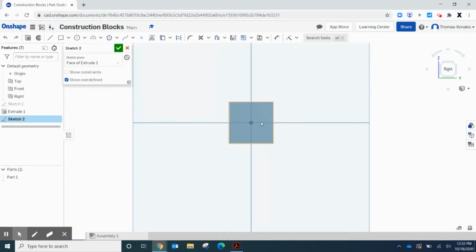And we're going to zoom in a little bit here. And what we want to do is actually add a sketch right on here that we're going to project off of to add a leg here. So we're going to use the rectangle. This time we'll use the two corner rectangle approach. So clicking up here to get our rectangle, we're going to go in this bottom corner and come up to this midpoint here. Okay, so I finished my sketch.